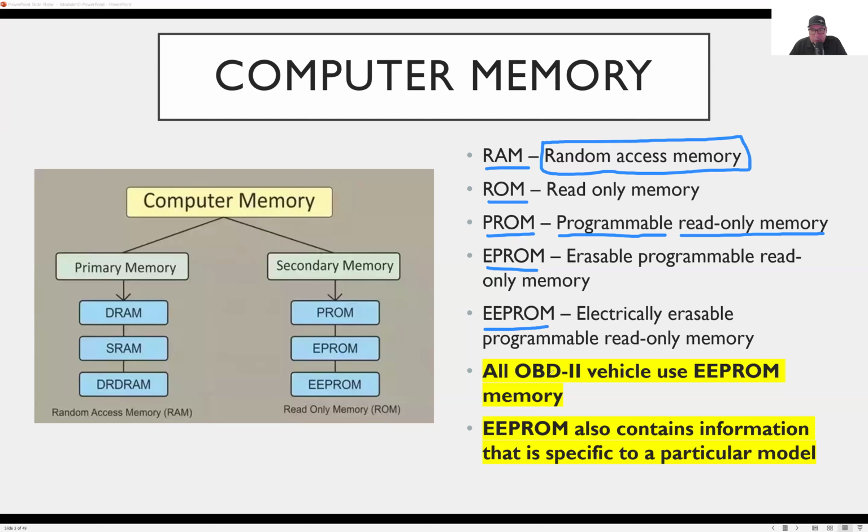If you want to research them, you're welcome to research them to get a little more information. Now, there's one acronym here I do want to cover, OBD2. I think I have mentioned this before, but I do want to mention it here as well. Onboard Diagnostics Generation 2. That's what OBD2 stands for. And all of the communication for us when we connect a scan tool is done through that connector. Okay. So if we want to program, reprogram, or update a module, we would have to go through that connector to be able to do it. So that's why it was listed here. Okay. And how it's connected to the EEPROM.